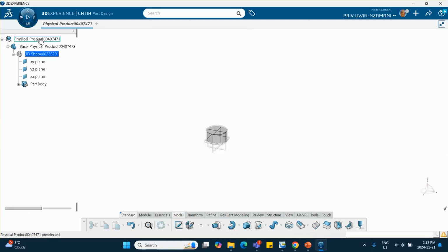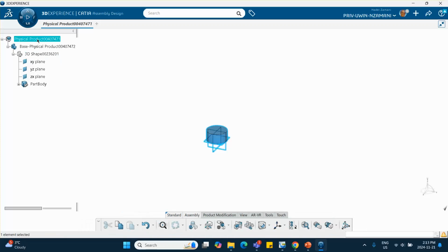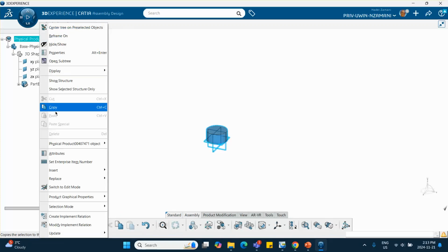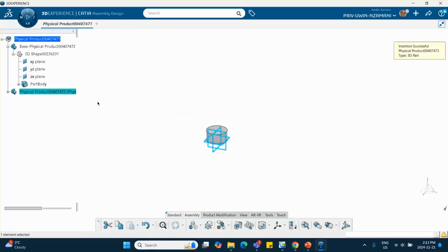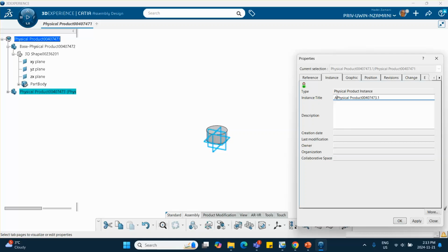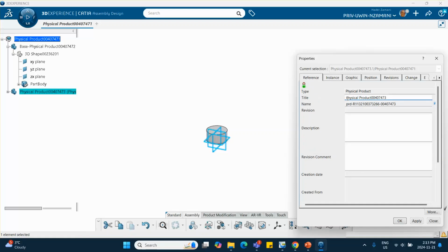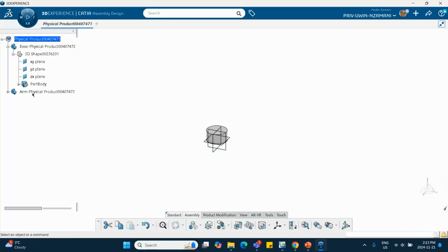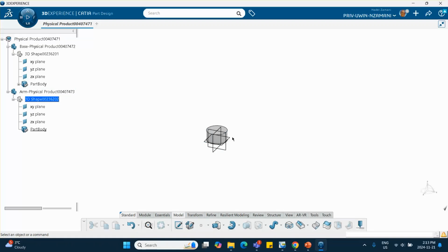Okay. Now I'm going to make the arm. So right click, insert 3D part. I'm going to go to properties and make this thing arm. All right, let's go make it. Double click on 3D shape. On a convenient plane, and convenient for me is right here, this plane.